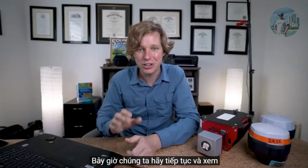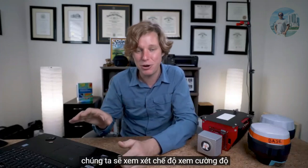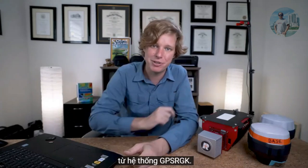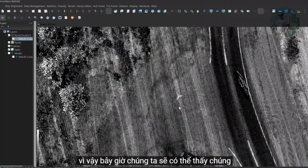Now let's go ahead and take a look at the accuracy of our LiDAR data. In order to do that, we're going to look at the intensity view of the LiDAR data, which will reveal the aerial targets, and then we'll be able to compare those aerial targets to the data we captured from the GPS RTK system. I just imported the ground control points into the data set, so now we're going to be able to see them laid right on top of the intensity view of the LiDAR data.